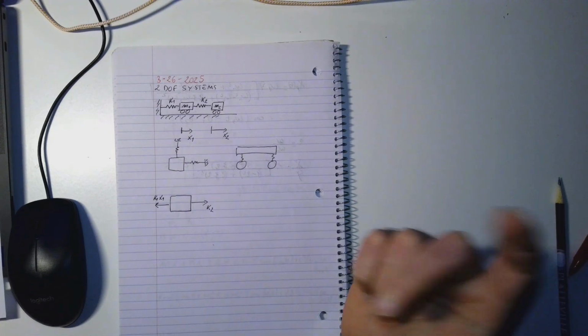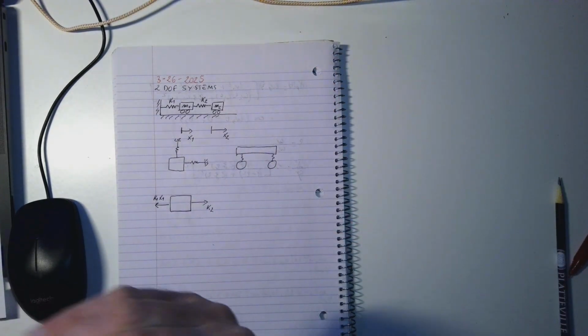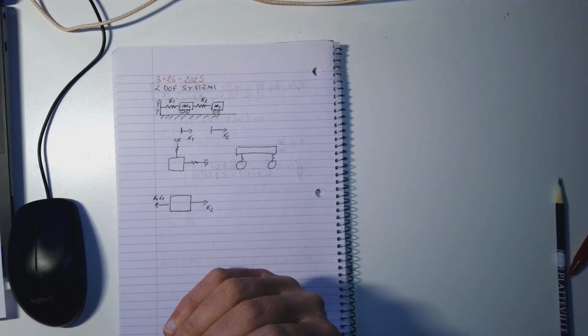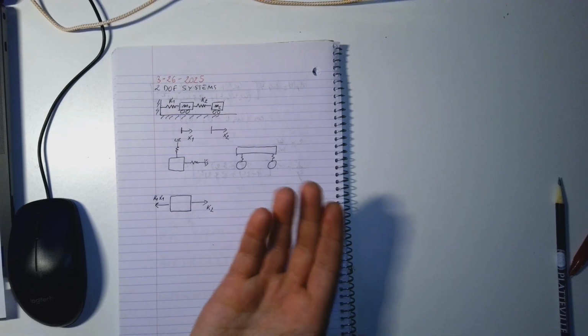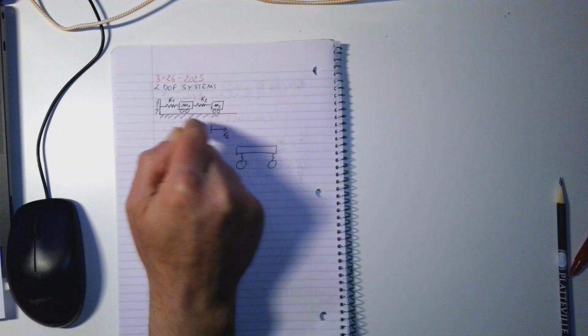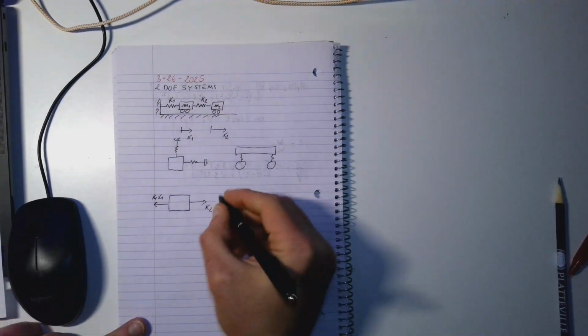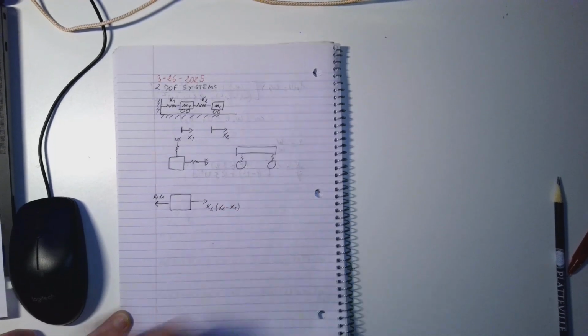Remember, this is the same thing that we said when we were talking about the base excitation. If in that case the mass and the base move by the same amount up and down, it means that the spring doesn't bring any force because it's not stretched or contracted. So what we should use to determine how much force comes from the spring to the mass is the difference of displacement between the two masses. So we have x2 minus x1.